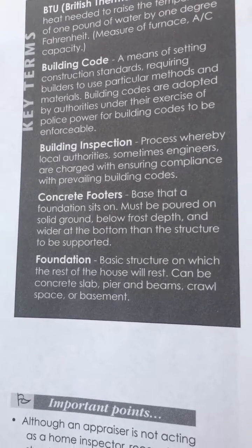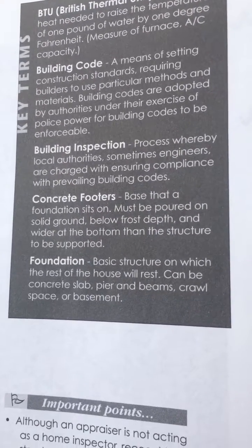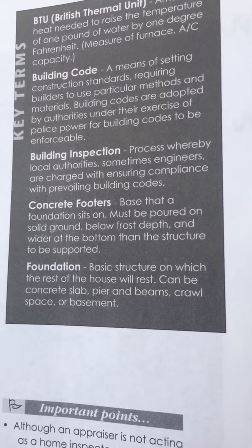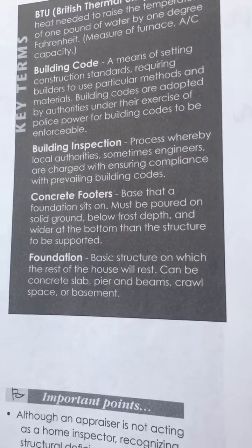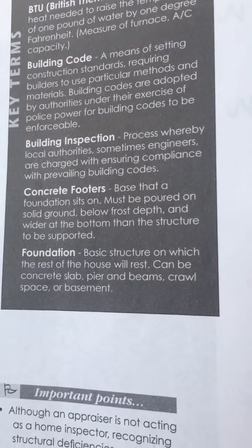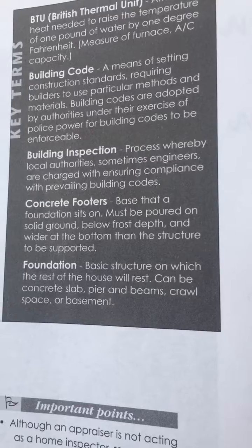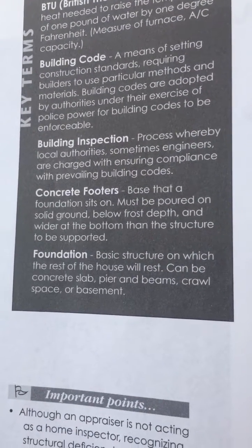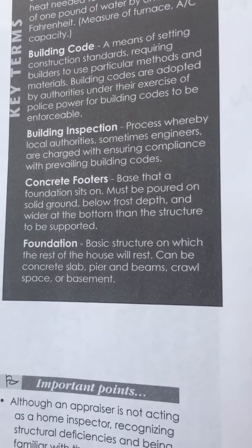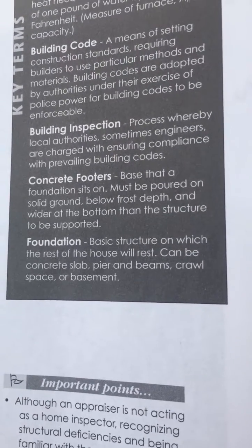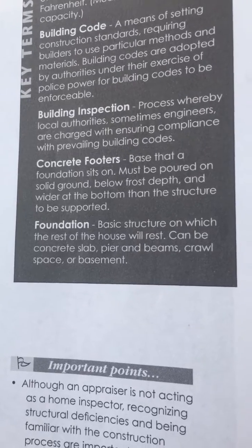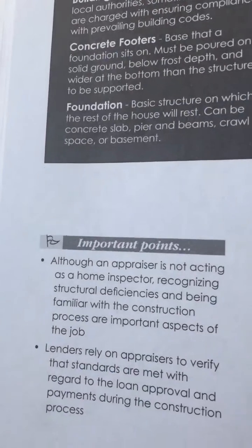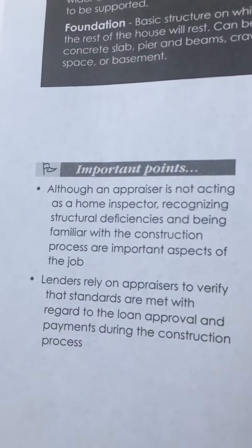Concrete footers, base that a foundation sits on, must be poured on solid ground below frost depth and wider at the bottom than the structure to be supported. Foundation, basic structure on which the rest of the house will rest, can be concrete slab, pier and beams, crawl space, or basement.